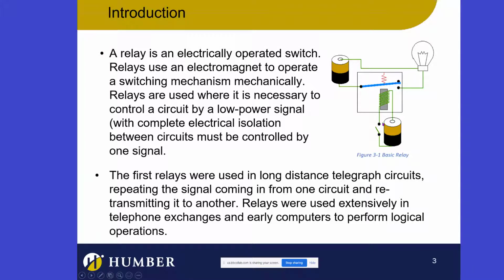And actually there could be a lot of current going through here. And this little switch could be like a little tiny micro switch, just running a few milliamps going through here, making a coil make this thing move. So this whole spring here, this throw goes down here with the electromagnet. So I'm actually controlling really high current with low voltage and low current. For instance, a doorbell. I could actually use a doorbell to control something that was really high current and high voltage. So that's what's going on.